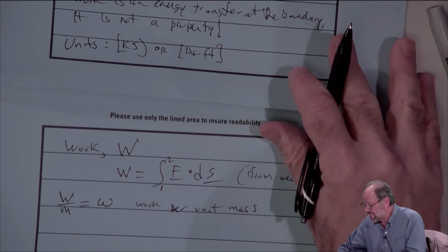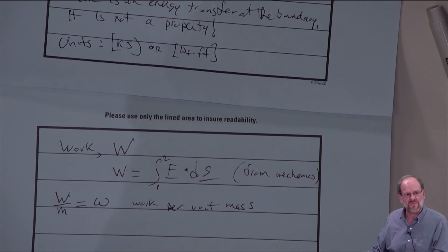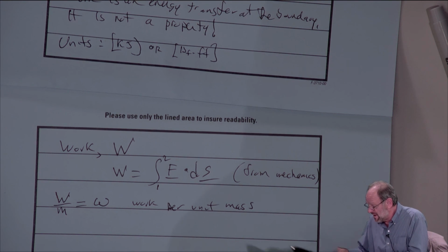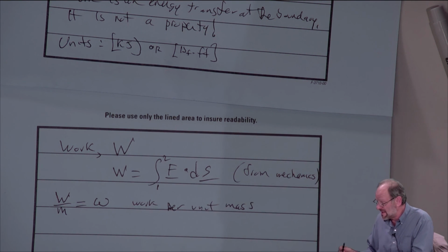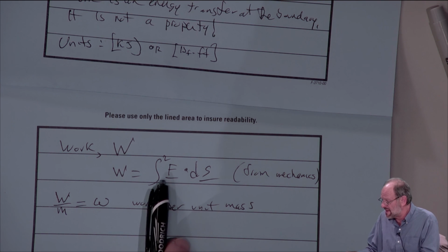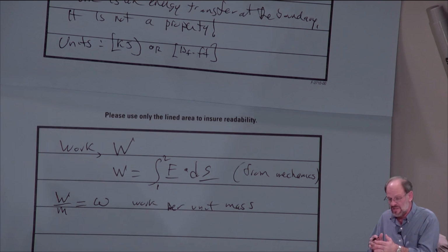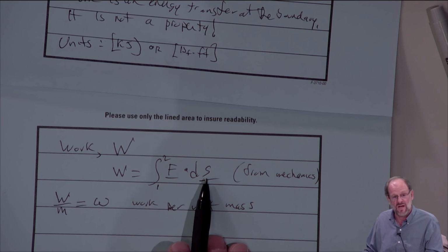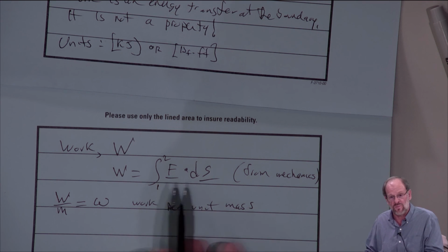Okay. Oh, by the way, it looks like I forgot my sign convention. So just to keep this in the same order, I should have talked about sign convention next. You'll notice here that if the force is in the same direction as the change in position, then both of those terms would be positive, so that the work numerically would be positive.